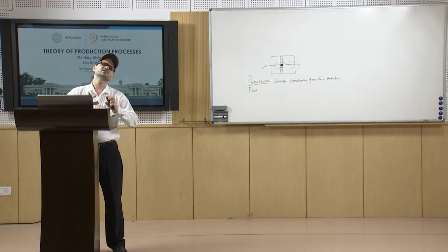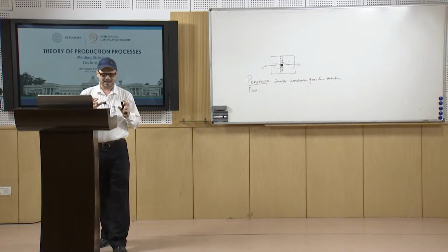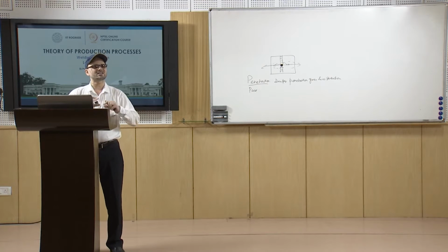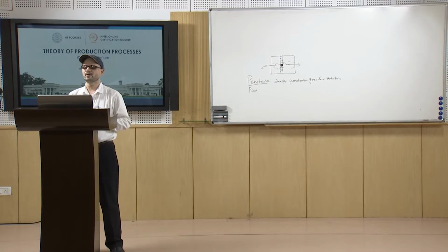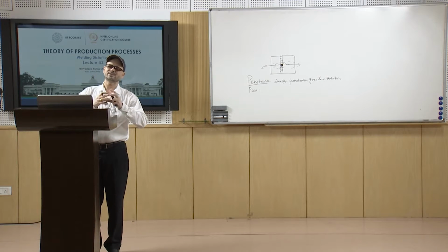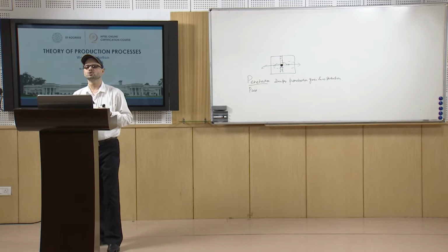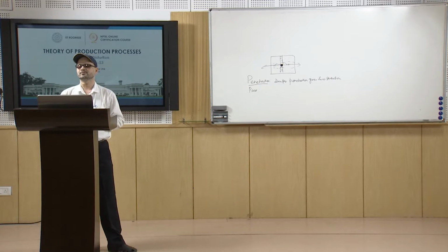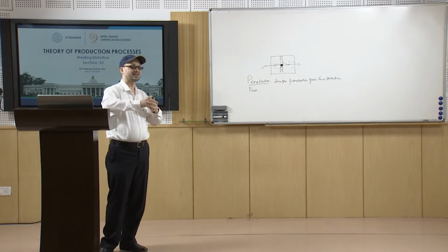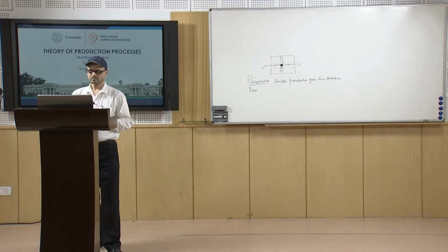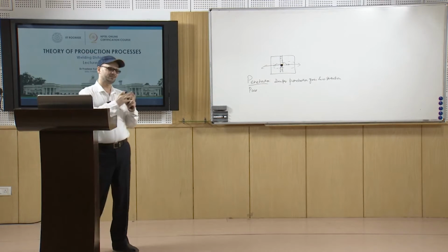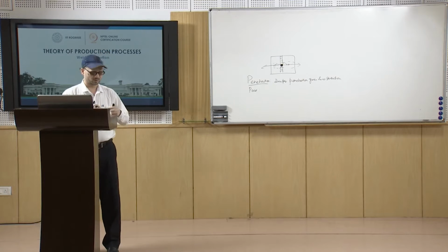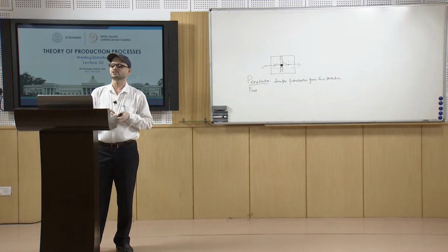We also talked about the edge preparation and fit up. So, we must have a proper edge preparation. As we discussed, we should ensure there is a minimum amount of weld metal, and the edge preparation should be as uniform as possible, so that you have consistency as far as the shrinkage is concerned. Along the joint, if the shrinkage is uniform, then there will be consistent shrinkage. So, that will lead to a lesser accumulation of these stresses.